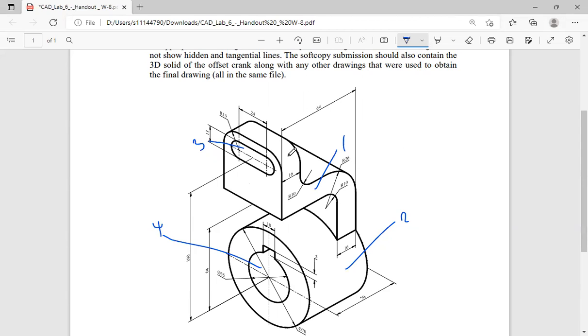So to draw this first shape here, we're going to use something called the sweep tool. So last week we covered the revolution and the extrusion options for 3D modeling. This week we're going to go into sweeping. So for sweeping, you need 2 things. Like on the whiteboard right now, you need to define the surface area or the surface, and then you have to define the path.